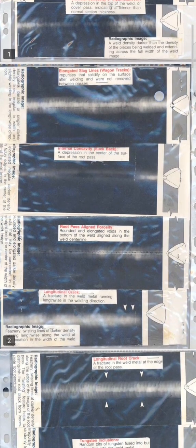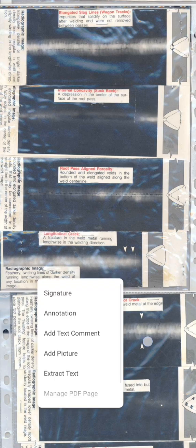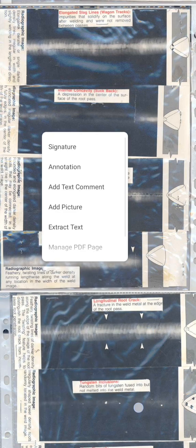Visual acuity is the ability to resolve a spatial pattern in an image. The ability of an individual to detect discontinuities in radiography is also affected by the lighting condition in the place of viewing, and the experience level for recognizing various features in the image. The following material was developed to help students develop an understanding of the types of defects found in weldments and how they appear in a radiograph.